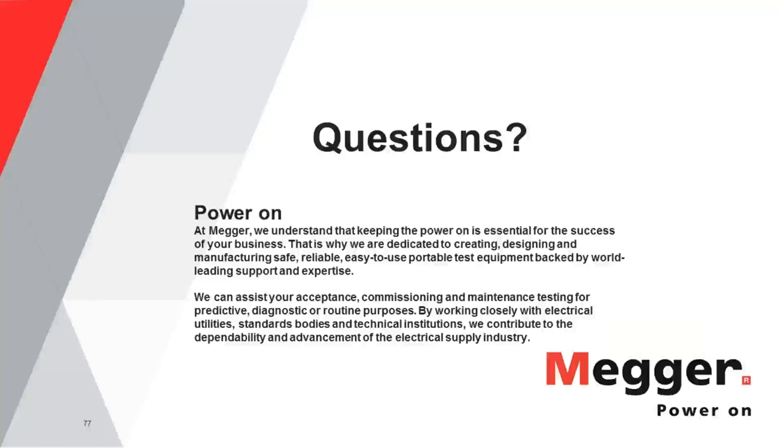Ground testers are at the other end of the resistance spectrum. So insulation testing is high voltage, high resistance. Ground testing is low voltage, low resistance. You want your ground rod to be as little resistance as possible. If you can get 1/10 of an ohm, that's wonderful, although it's hard to do, but that's the kind of thing you like to see. So ground testers are on the other end of the scale.